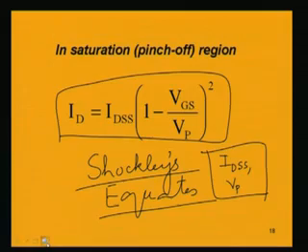And now, if we consider the drain to source voltage, the drain to source voltage should be such that it will be making the JFET device current or ID current in saturation. It will be in saturation, and the saturation region is generally used for amplification, like we have seen in MOSFET.